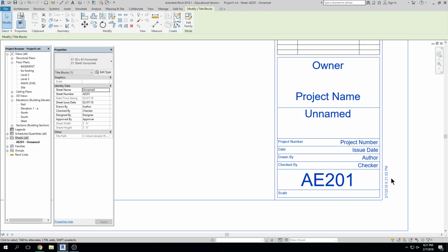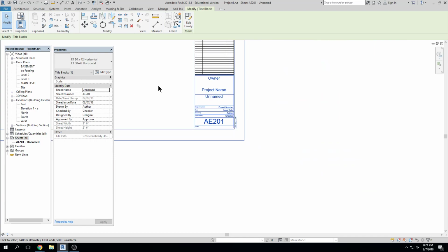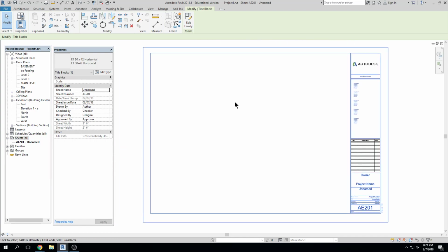okay? Now what that is doing is establishing this drawing sheet as AE201. And that's an important topic, because now anything that I put on AE201 knows that it's on AE201. So when I reference it with details or callouts, it knows it's on AE201, it knows where it's placed, and if you move it, it correlates the detail, it changes it to correlate it, right? It's nice.